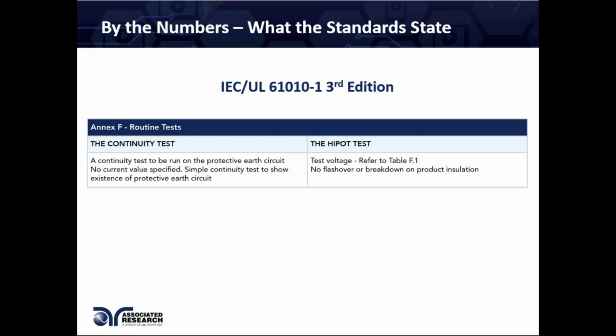I could just take a basic continuity, digital meter, a handheld meter, and check for continuity. So the requirement is not that strict. It's not giving you any numbers, any other parameters. It's just telling you to make sure the path is continuous.